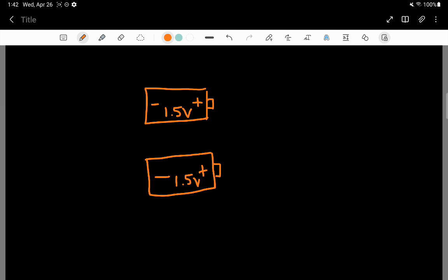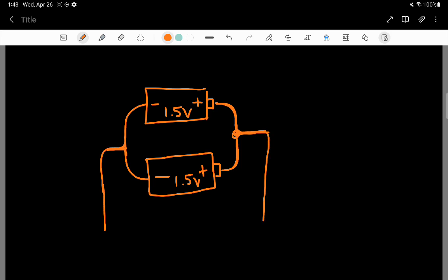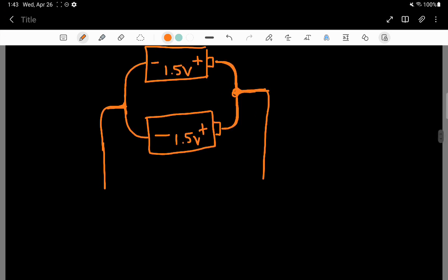I'm going to take a wire from the positive ends of both and connect them to each other with some sort of a weld or a touching connection, just a conductive connection. It's kind of like 2 wires merge into one. And I'm also going to make another connection on the backside that looks just the same. 2 wires merge into one. And now these 2 batteries are in parallel. And if I hook them up to a light bulb,